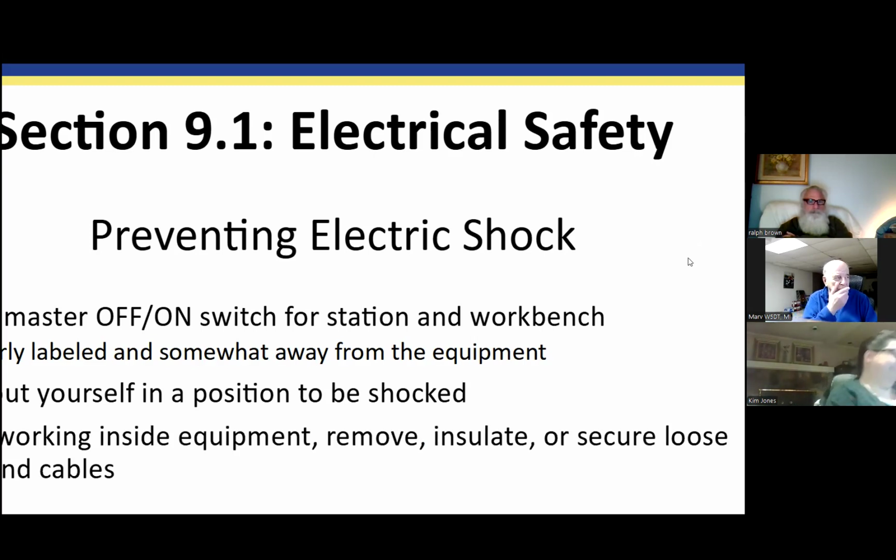So if you're experimenting and working inside your equipment, you've got to make sure that everything is insulated and you secure all your wires and cables, to limit the possibility of shock.